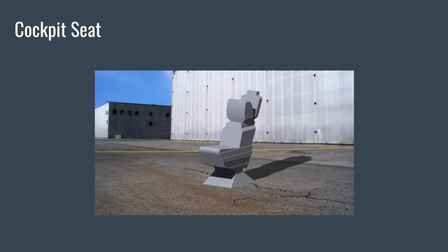The cockpit seat. The cockpit subassembly included two cockpit seats. A JPG file was uploaded to the sketch tracer workbench. With two sketches in both front view and right side view, the combine tool was used to make the cockpit seat a solid. A hole in the back of the seat and the floor of the cockpit were made to later apply a coincidence constraint and an offset constraint to keep the cockpit seat secure in place.